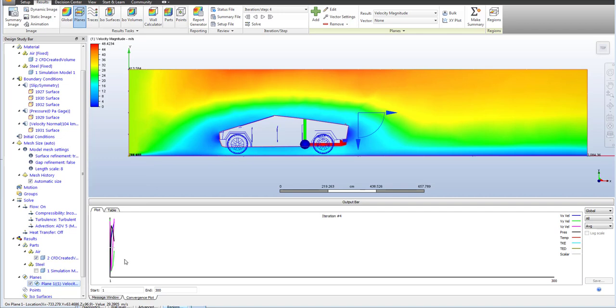Now it is iterating, and this is iteration number 4. It will iterate until it finishes, meaning it converges, or it reaches the 300 that we already set. If the result converges before 300, it will stop automatically according to our setting. But if not, it will continue to iterate until 300. Then we will see what the result of this simulation is, whether it has converged or not. Okay, see you in the next one.